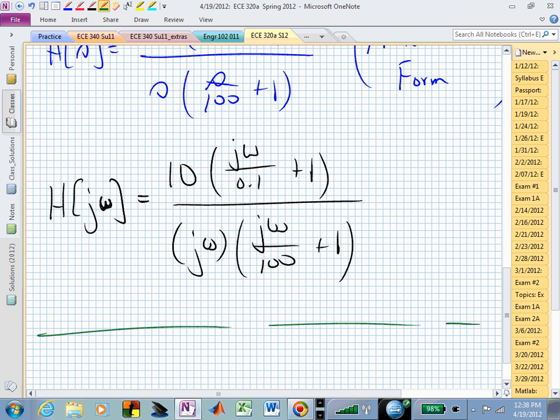So this gain hanging out there is not really the DC gain. This gain amplifies or shifts the whole transfer function up, but it doesn't really overcome what this guy is doing at low frequencies. This pole is causing everything to get really, really big when omega gets really, really small. Does everybody see that? So asking for the DC gain is the trick question on this. It's actually undefined. It's infinite.